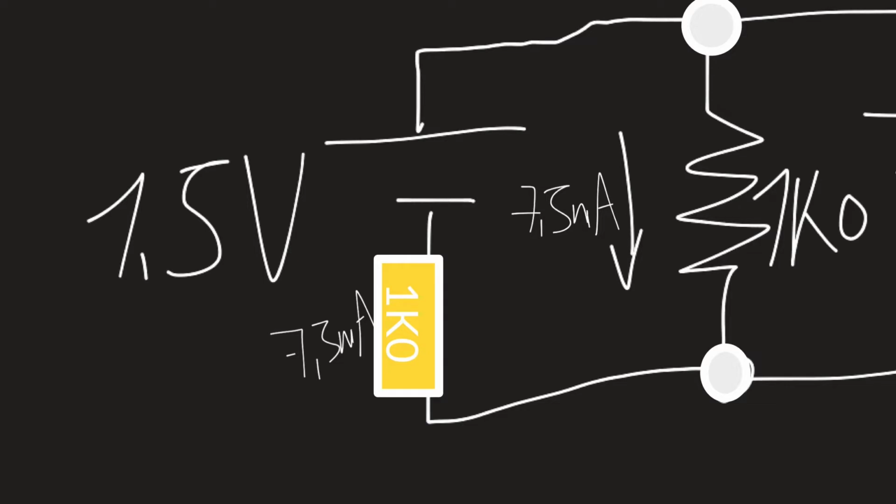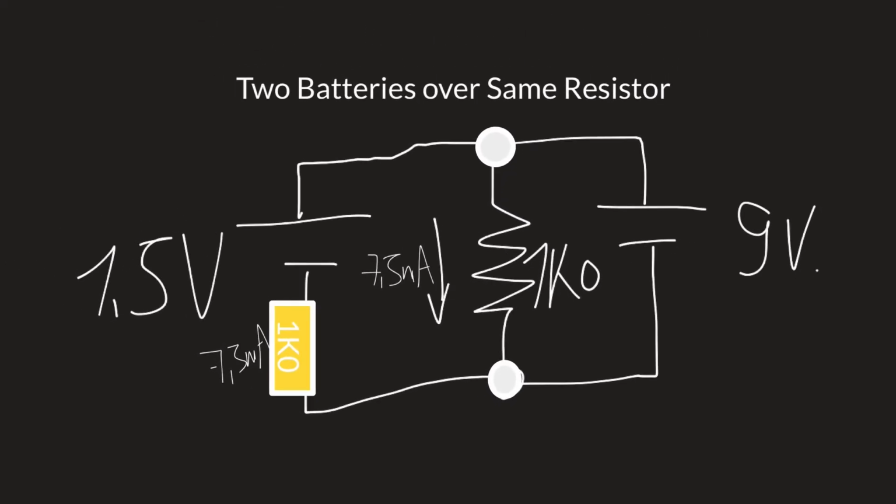We could say, okay, it cannot be that the current is flowing from here to there and then in here again, because if both are 7.5 milliampere, this would mean that there had to be a 7.5 volt drop across here, and then another 7.5 volt drop across here, which means in sum on that path a drop of 15 volt from here positive to ground.